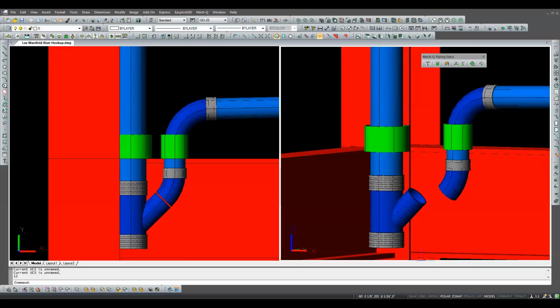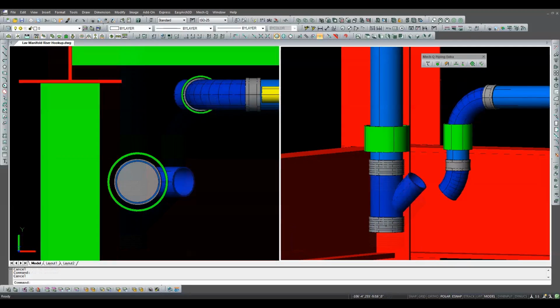First, let's move the Y back to its original position on the riser and change the left viewport to a plan view. This time we'll rotate the fittings before using the slide routine. In the case of non-90-degree fittings, on flat or vertical runs, with like-angled fittings as we have here, we can rotate the fittings in any sequence, but must never use the branch as the target for the rotation angle unless that fitting is at its final rotation angle and elevation.